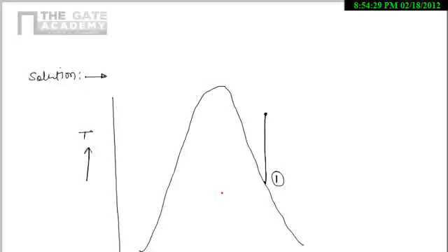It means 20% of the steam, 0.2 m, is extracted from point 1 as per the problem, and then after that it again does work. The remaining steam, 0.8 m, now enters the condenser.